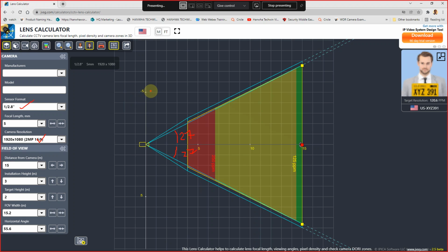Okay. So if you do this for one project, you will find out that it's the same for every other project because the coverage actually depends on these parameters, focal length, resolution, and sensor, not really dependent on vendor models. Very slight impact, but it's not really dependent on that. That's why we don't have to choose any vendor. You can still do the coverage because it's just formulas which tell you how much you can cover, mathematical formula.